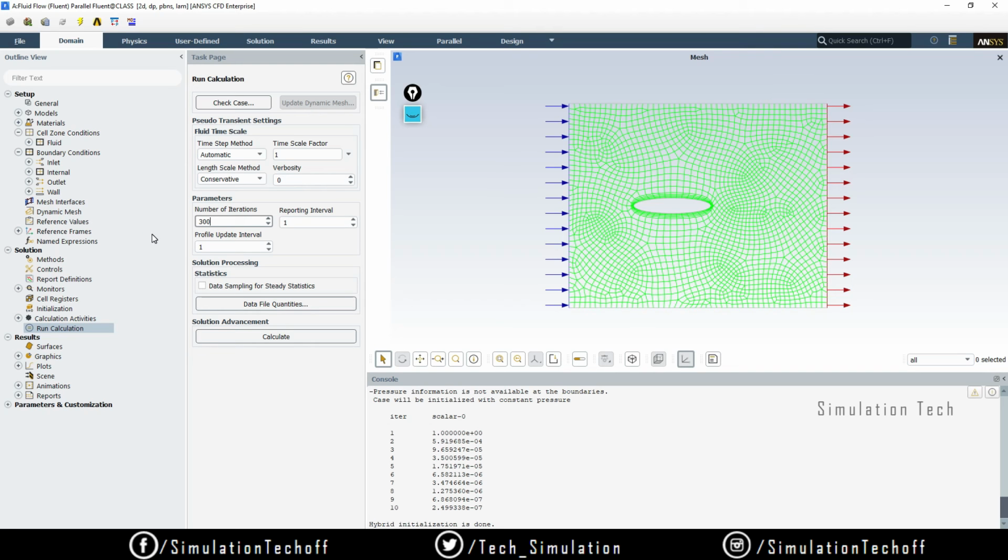So there are no search recommendations. Sir, how can I assume that iteration factor? You can give any iteration factor like 100 or 200 or 300 or 400 mostly. The problem convergence will greatly depend upon the quality of the meshes and the reliable boundary condition factors. So what is a reliable or appropriate boundary condition? In some cases, you may give a boundary condition which is beyond the limit.